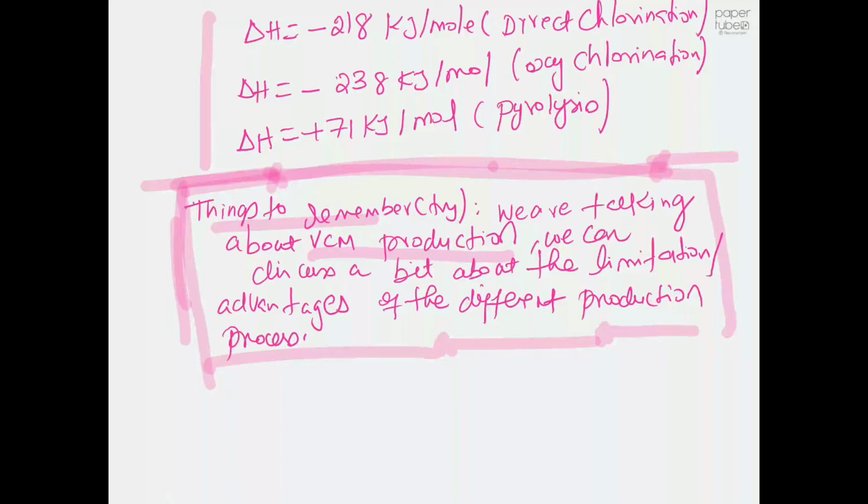Before touching the Aspen HYSYS software, you really need to know the in and out of the process. Yeah. So you really need to know what goes inside, what comes out, what could happen during the process. Maybe your product may degrade, for example, or you may lose your product due to combustion in this case, or you may get some other side products. You may end up with a lot of impurities due to some unwanted reaction that may happen during the course of the chemical reaction. Yeah. So these are some other information that you should be aware of.